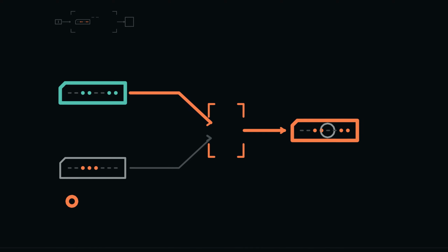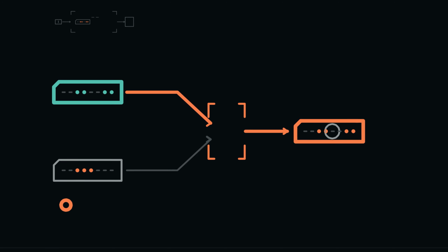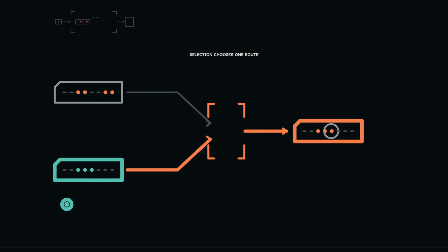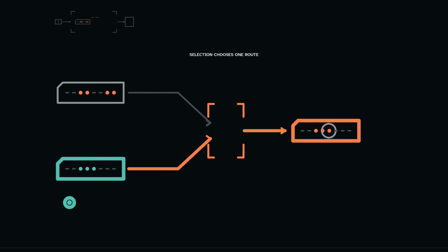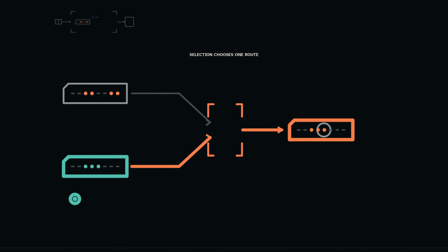The selector's promise concerns which position is followed, not which numerical value is preferred. There are 8 complete input rows because A, B, and select each have 2 possibilities, 2 times 2 times 2. We do not need to memorize 8 unrelated answers.